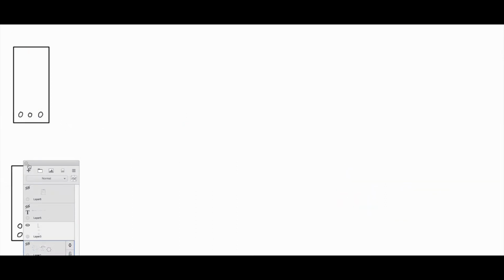Number 7 actually is dependent on the bar spacing. Guys, when we do the reinforcement, we have to leave a spacing. We have a clear spacing, which is from the end here of the bar. The clear spacing is from here to here. The ACI specifies that this should be 1 inch at least, or equal to the bar diameter. Okay, this is called clear spacing.